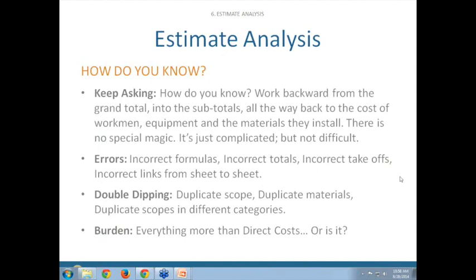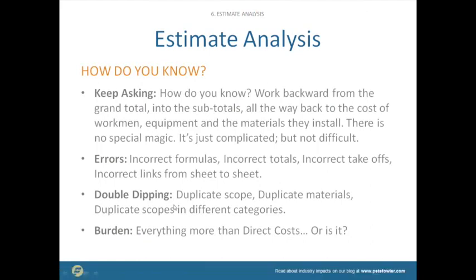So, estimate analysis: keep asking, how do you know? Work backward from the grand total into the subtotals, all the way back to the cost of workmen, equipment, and materials they install. There is no special magic to this. It's not even a technical exercise. If you're a lawyer or a property manager, you can absolutely figure out if somebody's estimate is a good one. Why? How do you know? How much is that? You can just keep asking why. Errors in estimates are more common than not. I don't have time to go into these details because we're only one minute from done.